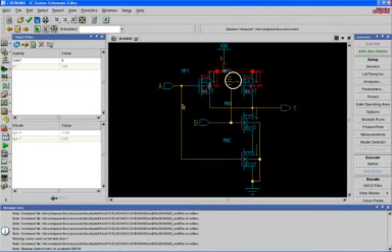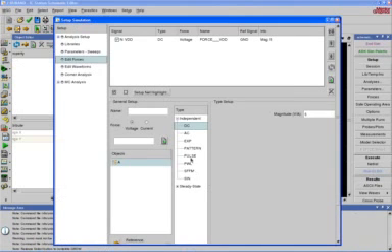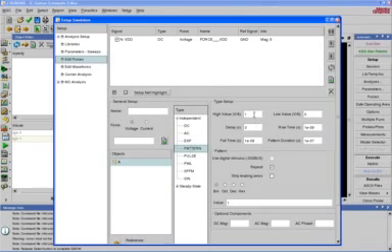Now let's select A. Go back to the setup simulation window. On A, we're going to set up a pattern that goes 0, 1, 0, 1. So let's click on pattern. Change the high value to 5. Delay can stay 0, low value to 0. Rise time and fall time can stay the same, so can the pattern duration. So the pattern is going to run for 100 nanoseconds. Okay. Repeat the pattern. Go change the binary and add in 0, 1. Okay. So add a 1.